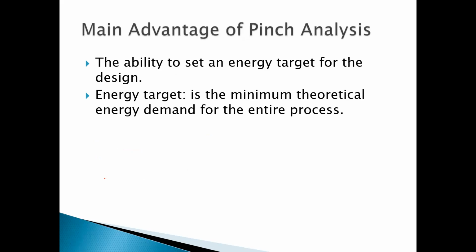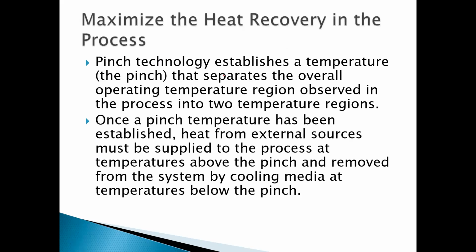How do we do this? First, we need to set up the energy target. What is the energy target? The minimum cooling and heating utilities requirement. This is what it means. So how do we do this?